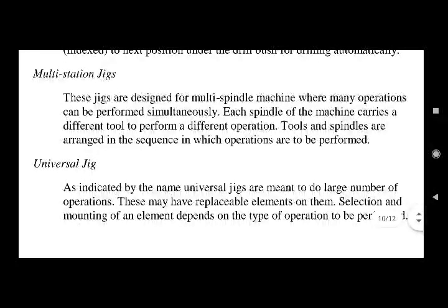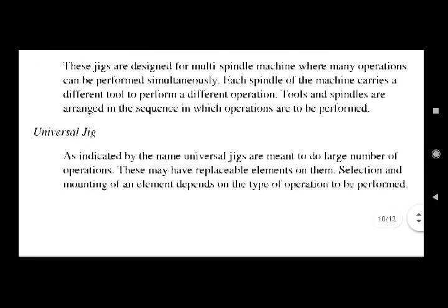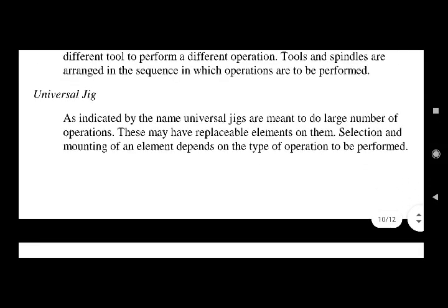Multi-station jigs. These jigs are designed for multi-spindle machines where many operations can be performed simultaneously. Each spindle of the machine carries a different tool to perform a different operation. Tools and spindles are arranged in the sequence in which operations are to be performed.